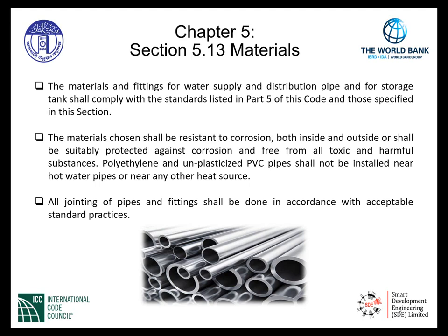Polyethylene and unplasticized PVC pipe shall not be installed near hot water pipes or near any other heat source, due to the fact that these materials will combust, they will melt, they will deform near high heat sources.